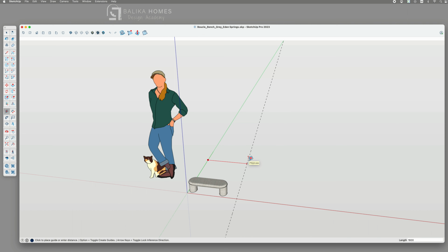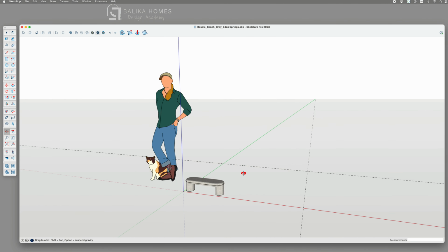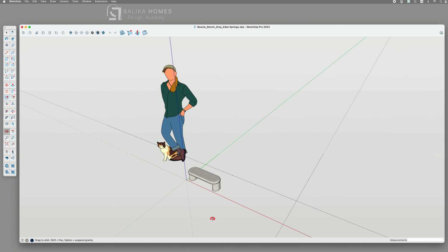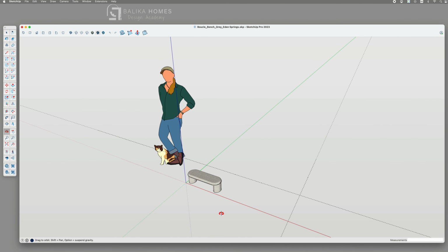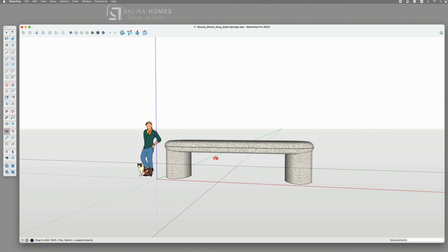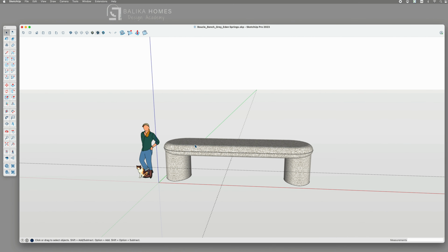So to address this, I initiate the creation of guides in SketchUp using the tape measure tool. By holding down my arrow keys, I can meticulously establish the furniture width, length, and height of the objects. Now imagine a scenario where a piece of furniture appears either too large or too small upon retrieval from the warehouse. Such issues won't happen if you download some of my pieces, but occasionally you will meet those oversized dinosaurs in the warehouse.